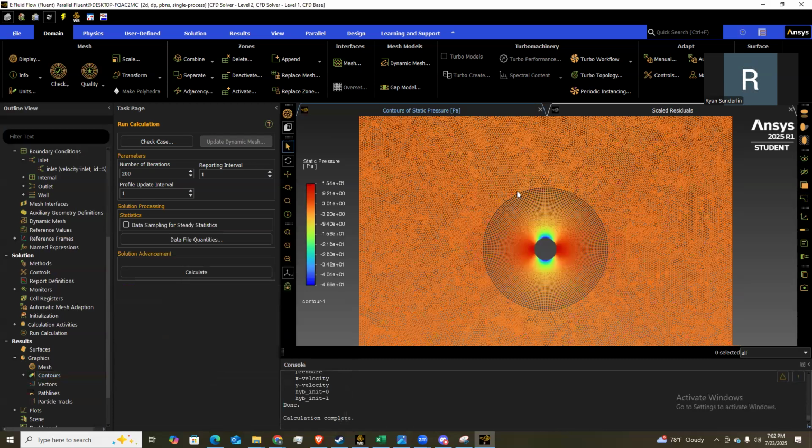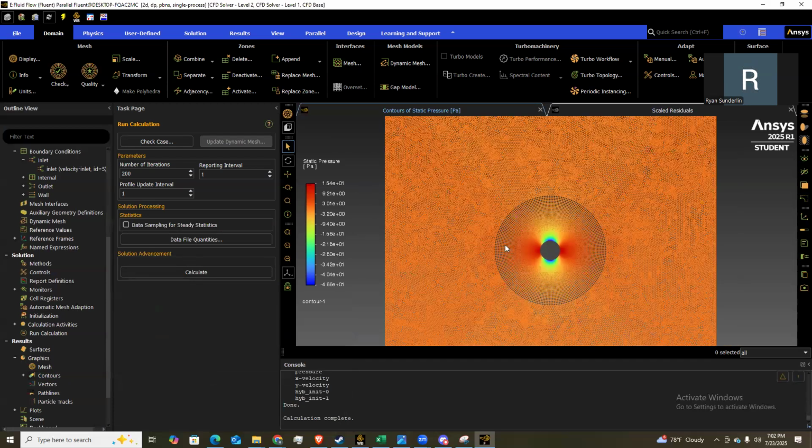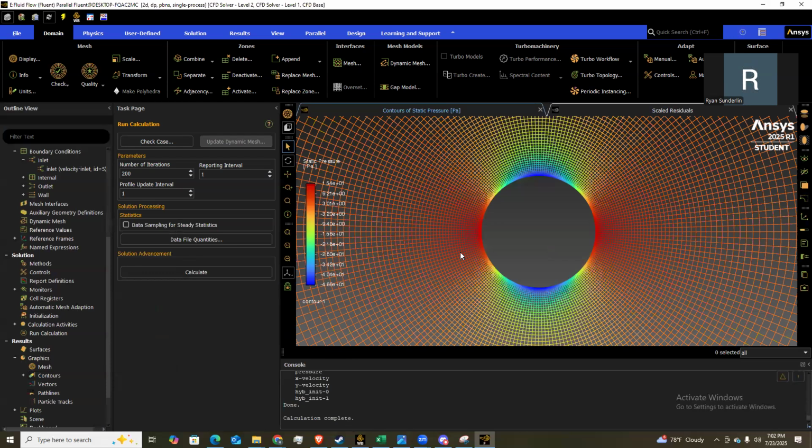You want a nearly perfectly symmetrical pressure distribution because it's inviscid. The boundary layer is entirely attached as it flows around the cylinder. So the stagnation point here, and then the velocity reaches its maximum, aka the pressure reaches its lowest, top and bottom. But since the boundary layer is attached all the way around, there's another stagnation point at the back, which correlates perfectly to the theory.